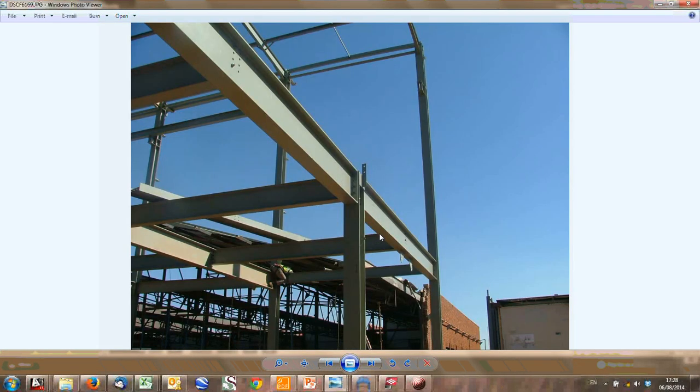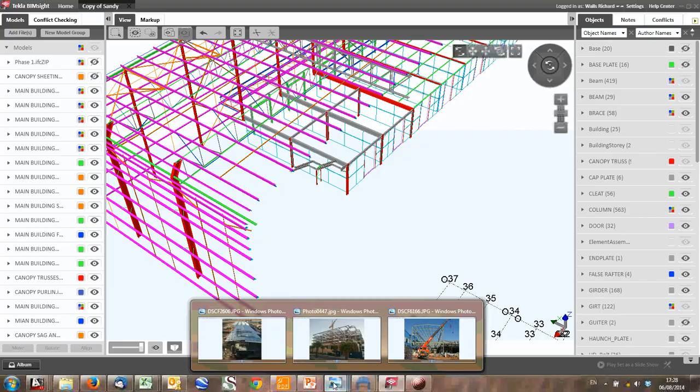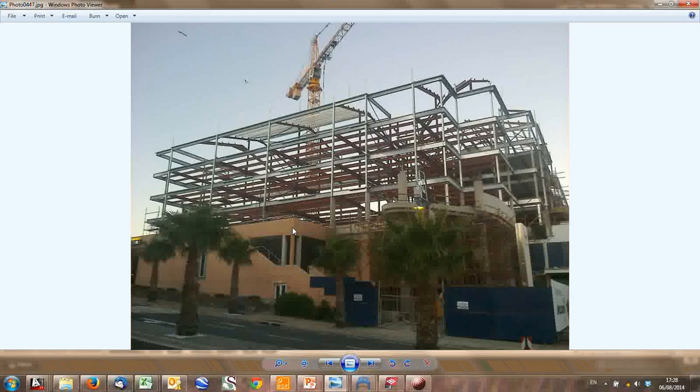So now we're going to have a quick look at some other constructed buildings. This was one I walked past that's at the Cape Town waterfront. I wasn't involved with it, but quite a nice looking structure. Just a simple composite structure. These are probably fixed connections or haunched connections on top, steel sitting on concrete, etc. There's currently no bracing. I don't know whether they'll add bracing in the future or they did before it's finished.